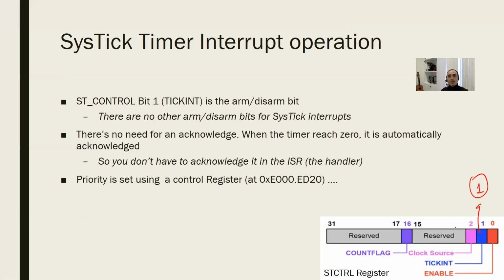For this device, since it's an interrupt source, there should be an interrupt priority as well, right? It should be numerically lower than the priority defined in BASEPRI. You remember the priorities. It is written into this address. Why this address? Because when I was preparing these slides, I checked the data sheets.